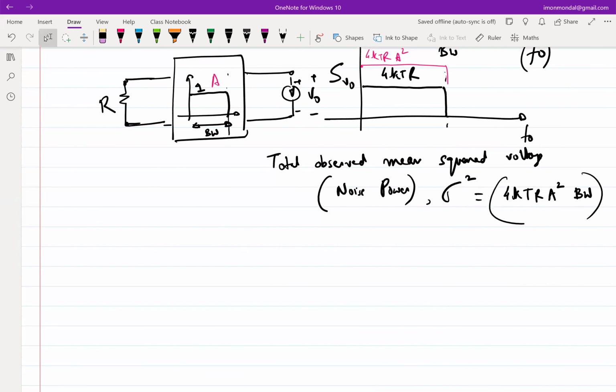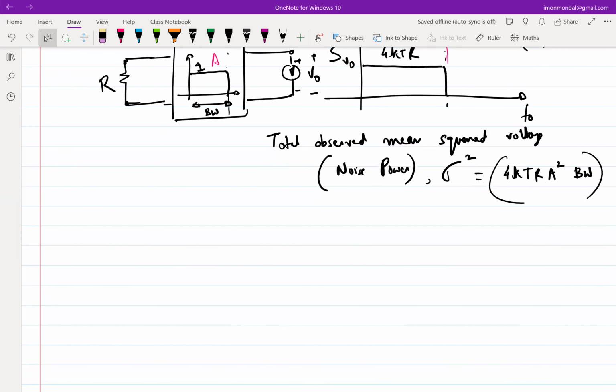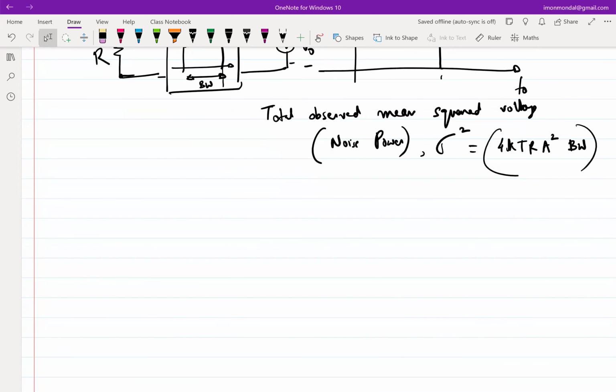So now this is as far as the noise from a resistor is concerned. Okay, but we are not limited to the noise from a resistor only. As it turns out, any element, any dissipative element, I'm not proving this again, but as it turns out, any element that dissipates power is noisy. Which essentially means that a capacitor is not noisy, an inductor is not noisy, but a resistor is. Similarly, a transistor is, right? A transistor also dissipates power, right? So it's noisy. So if I talk about a MOS transistor,